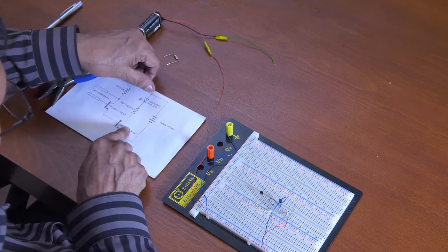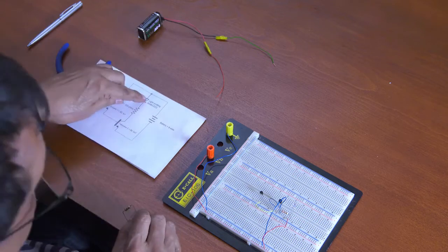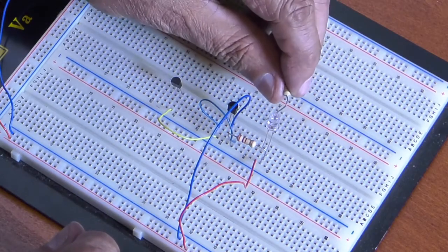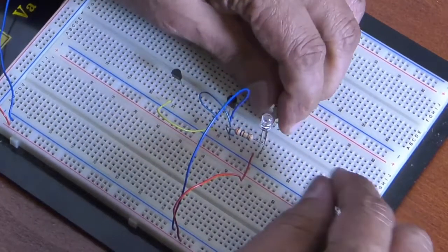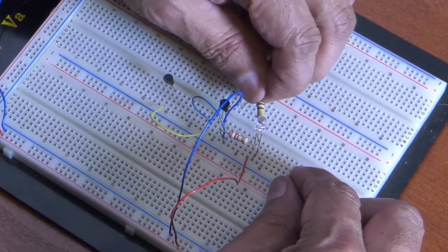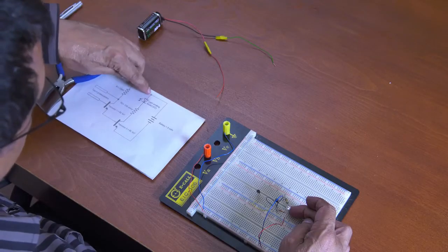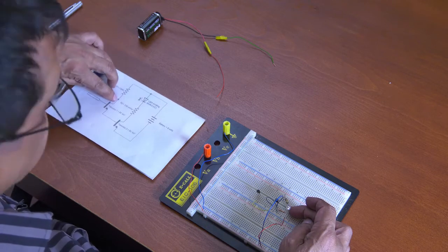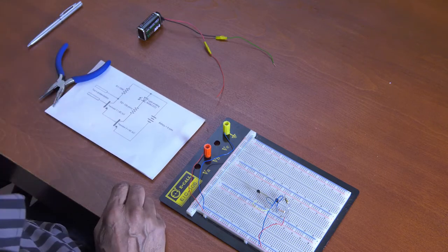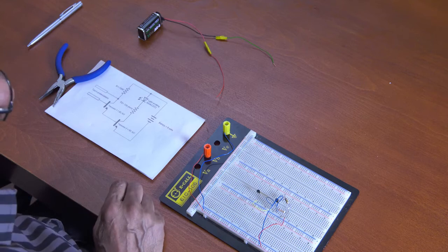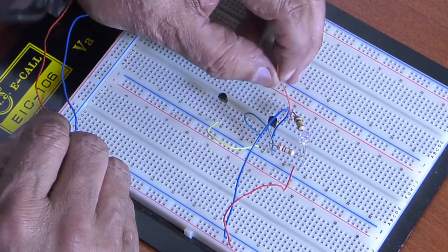From our anode, we're now going to join a 100K resistor. This is a 100K resistor. So from our anode, that's why it's always important to have the anode facing in one direction, so you know exactly where it is. You don't have to pull the LED out again. So I'm just going to go there and go to a neutral point, like so. So my 100K resistor is connected to my anode, and the other end of that resistor is connected to the collector of transistor number 1. If you know your breadboard well, this will go well.